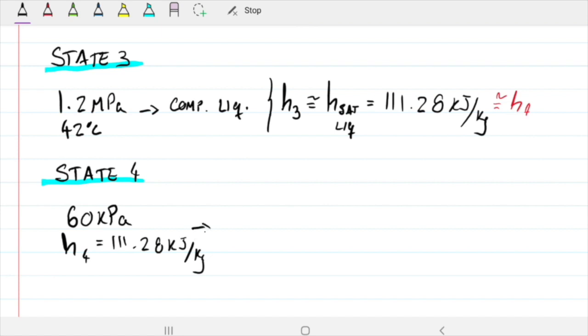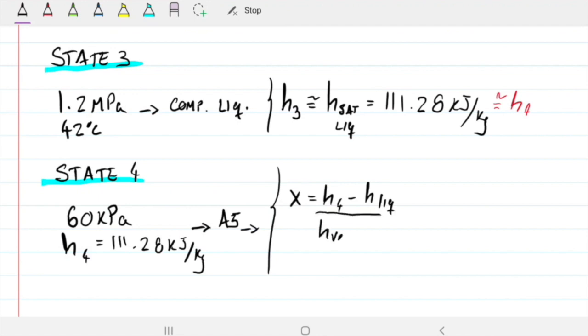Okay, and knowing that, we can go now to the pressure table, table A5. We know it's already a saturated mixture, but we can be extra sure by noting that our enthalpy falls between the saturated liquid and saturated vapor. That means we can go ahead and do this, and with this we can grab our quality, and quality ends up being 47.97. And that's the first part, right, because it's asking us what's the quality at the inlet of the evaporator.